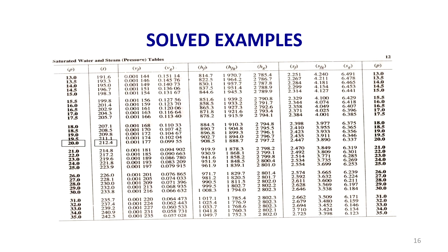You can see here the first column is the pressure. So, at 20 bar, the saturation temperature is 212.4 degree centigrade. This is table number 2.